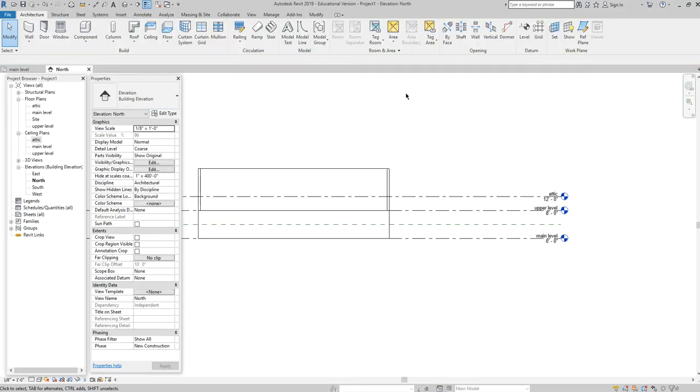Everything in Revit is associated with a level. So whether it's plumbing fixtures or doors or windows or walls or a roof or, you know, a floor plate or a foundation, everything is defined by a level. And so that's why it's so important to get them correct, okay?